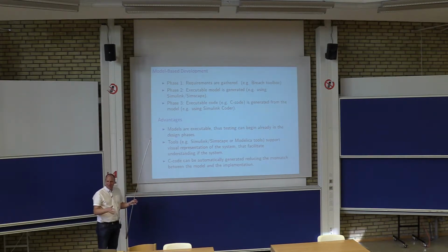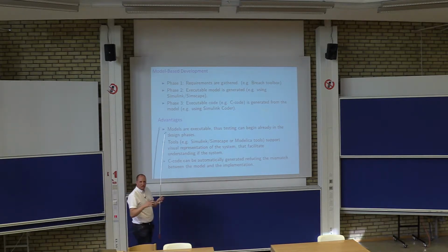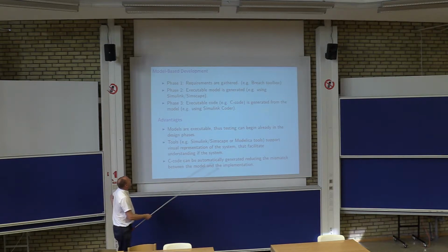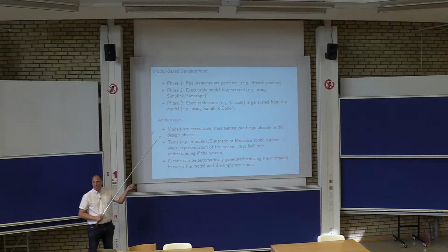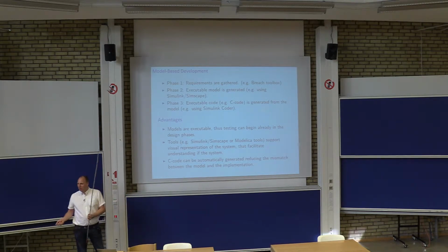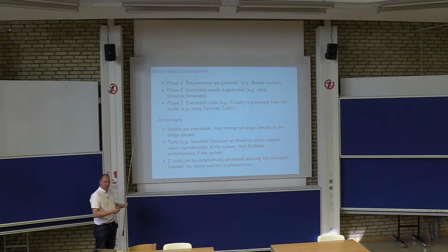Model-based in the sense that you have models of the code and the plant and the requirements, and then you can evaluate everything on the closed loop system on the models only. And then typically what you would like to do is to combine this with code generation. So you don't have to write the code yourself, but you can rely on these high-level tools to do it.